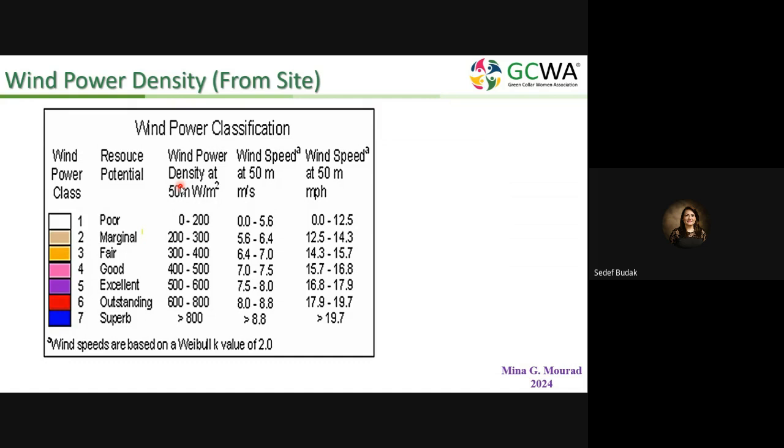Because of that, the most popular measurement towers and systems now start from a minimum of 100 meters, up to sometimes 150 meters, because on the sites we are trying to measure the winds at the correct level where we are going to place the turbine, to be able to calculate the energy production. The turbines and measurement towers are getting bigger and taller. It wasn't like previously when I started. It was only 10 meters, 20 meters. Now it's 10 times more.